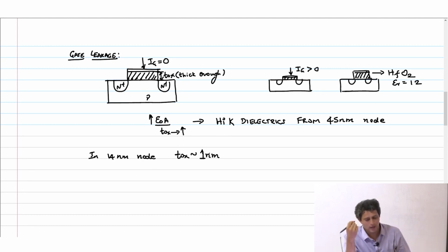So typically as a designer now you don't have to worry about gate leakage so much, unless you are doing some non-volatile memories and stuff, wherein you introduce defects, when the gate leakage can go up. But you should be aware that this could be a potential problem and you can't take it for granted that the gate current is 0, okay. Any questions?